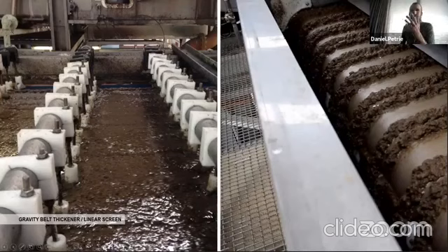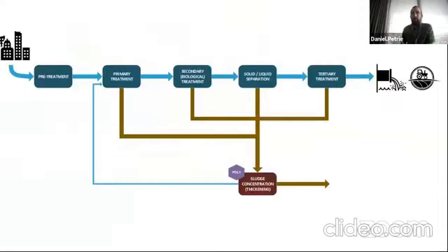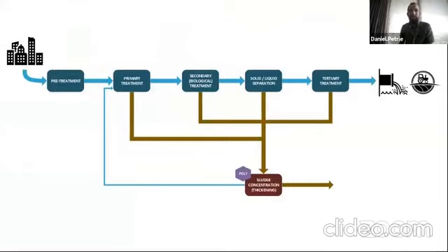There are other technologies as well, like flotation, but we're not going to get too deep into that. I just want to emphasize that some of those thickening processes may require chemical addition. They typically aren't very energy intensive. That comes later. So now you've got this thicker solid stream, which is good, but what happens to all the liquid? Well, that liquid's got to go somewhere. And it's definitely not clean. So typically, we can return that back to the wastewater treatment works, back to the head of the works.